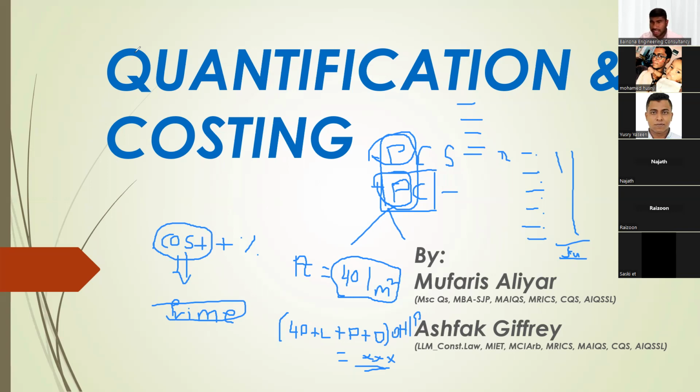To make this process easy, the project contractor is also given a vendor list. So the contractor doesn't have to go to 10 shops in the market during the estimation process. The vendor list is given, maximum 3 or 4, 5 maximum. The vendor list is given by brand name plus the local supplier and the email ID or phone number of the supplier. So the contractor can easily reach the supplier. He can send a message or an email to the supplier attaching the specification. Please provide a quotation. We will talk about that process, how you do evaluation, once you receive the tender. So I'm just touching upon that, so you can price it.